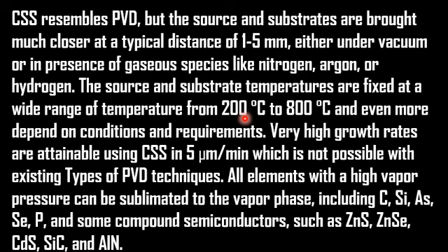If we slightly heat the substrate material from room temperature, then when the material evaporated from the precursor material is deposited, the slightly higher temperature of the substrate will make the deposited film easy to diffuse inside the substrate. So in this way we basically get a good quality thin film with better adhesion.